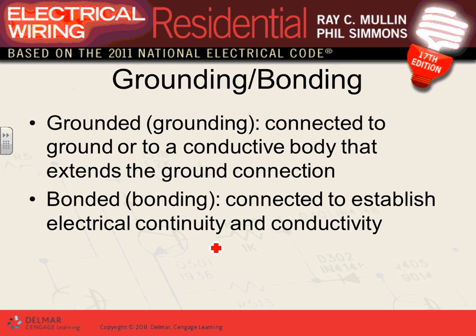And we'll talk about grounding equipment versus grounding the system, guys, a whole different thing. Grounding the system, when you have a Y system that is grounded, we ground it to stabilize the voltage to the ground. For example, you want to get 120, you better go ground the system so it can give you 120. Meaning the center of the Y has to be tied to the ground to stabilize the 120 that you're getting. Again, we'll talk about this one